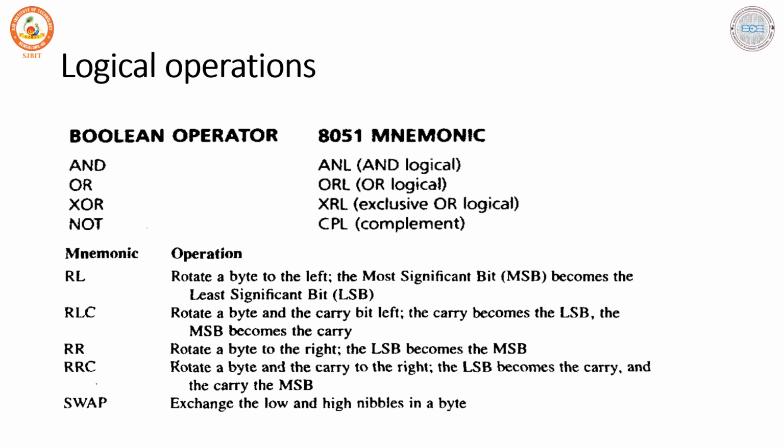Consider the logical operations. We talk in terms of binary logic. Binary logic defines the value 0 as low and 1 as the logic level high. Any electronic circuit normally defines binary value 0, which is equivalent to 0 volts, and binary value 1, which is equivalent to 5 volts. Hence, using transistors as building blocks, we make use of several electronic circuits, and gates are designed. The property of these gates is that there are one or more logic level inputs, and similarly there is one logic level output.